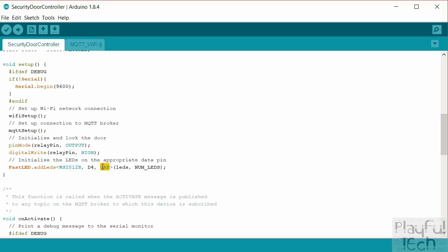So rather than RGB, which you might think is more common, this is actually GRB byte ordering. If you get that wrong, all that's going to happen is that instead of displaying the color red, you're going to get the color green appearing instead. It won't really do any harm, but it'll just mean your color calculations are all a bit off. So if the colors look weird, you might want to try changing the byte ordering of your color value there.